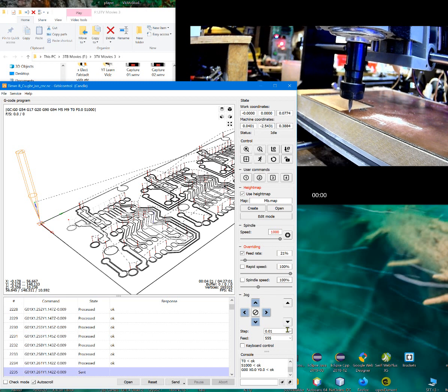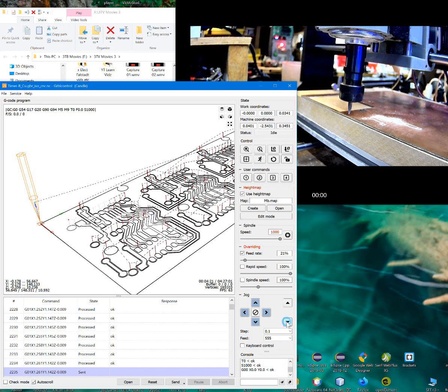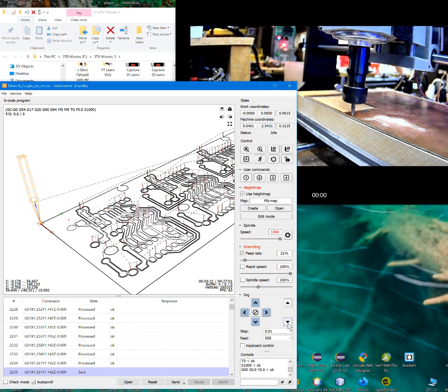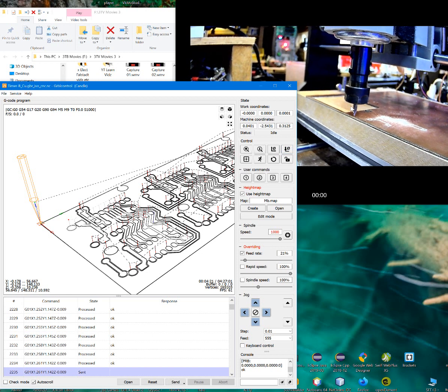Yeah, I don't know if I want to sit there and do that all day. 30 mil. Got 6 mil right now, so let me go to a smaller increment. That would be another 1.5 mil, and hopefully that's enough to let me zero it there. And anyway, that's how you adjust your axis up in the positive direction.